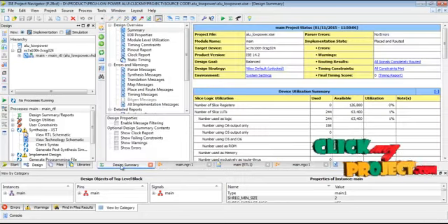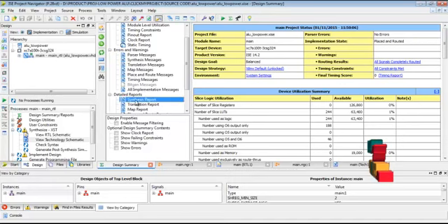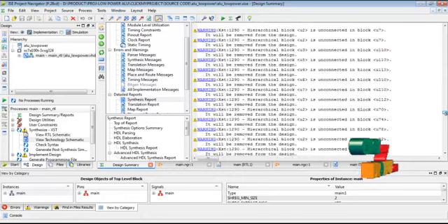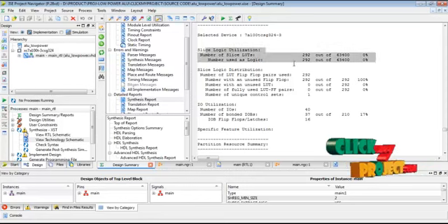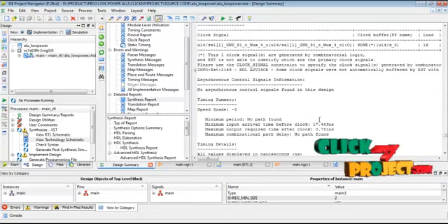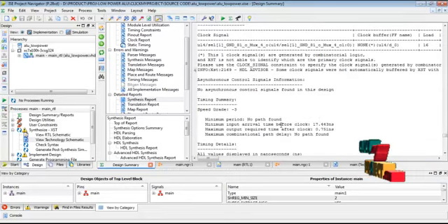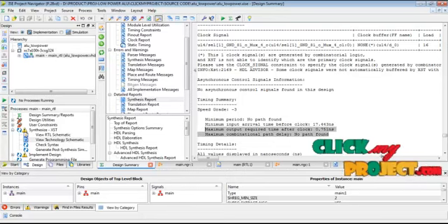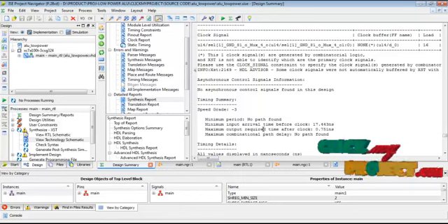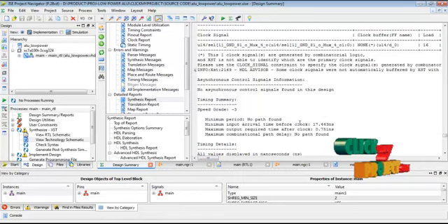Then we open the design summary, create the synthesis report results and open the synthesis report. It shows the device utilization of our ALU architecture: lookup tables and flip-flop pairs, then the bonded input outputs. These results give the area for our process, and then the latency level. This section is mainly used for the timing summary of the ALU architecture process, showing the delays before and after the clock due to the running of each and every LUT function in our ALU architecture process.